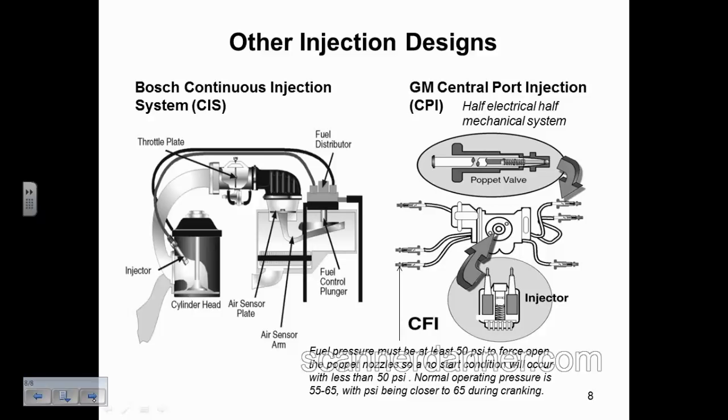And so what we had was a variable pressure in our line and in our components here to control fuel. And the way it was done, you had this fuel distributor, as the picture shows. There's an air plate here, and as you open the throttle, air would run into here and lift up on the plate and go into the engine. When it did that, it moved this spool valve that was in here and put more pressure to the injectors. That was how it was done.